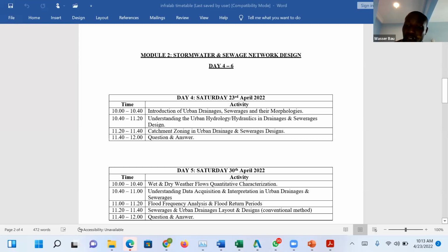Sometimes people build what we call a primary sedimentation tank, or a combined sewer overflow. There's no treatment whatsoever. Then from there, you take it to the open stream, open drainages, open river, and discharge them with no treatment, because they are not